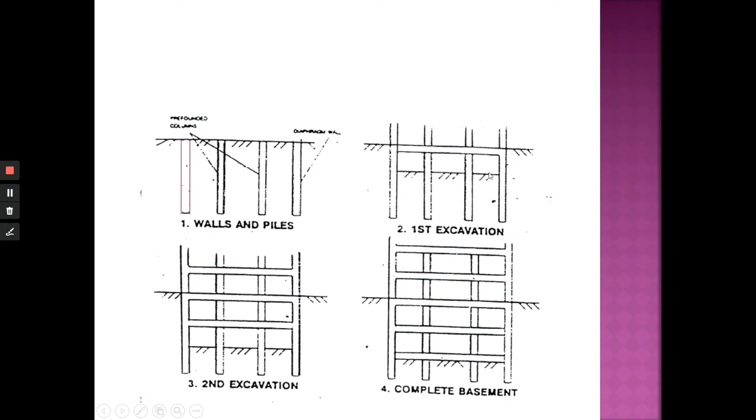The first excavation, and then they will construct the slab of the, what is this? The first level. Yeah, the first level of the basement. So you see here, you can see here that this construction is being done from the top to bottom. Okay, from the top to bottom. This is not conventional. This is top down.